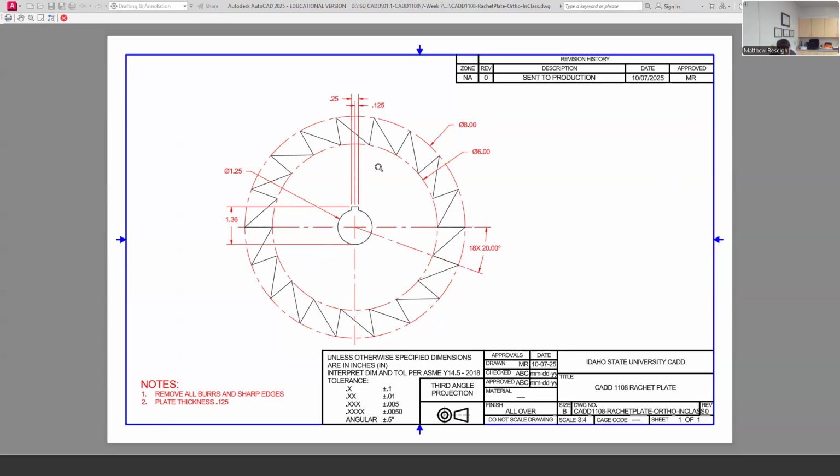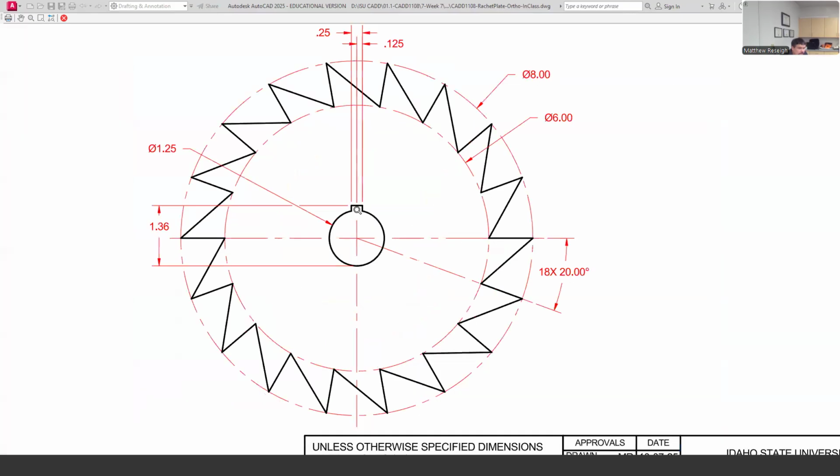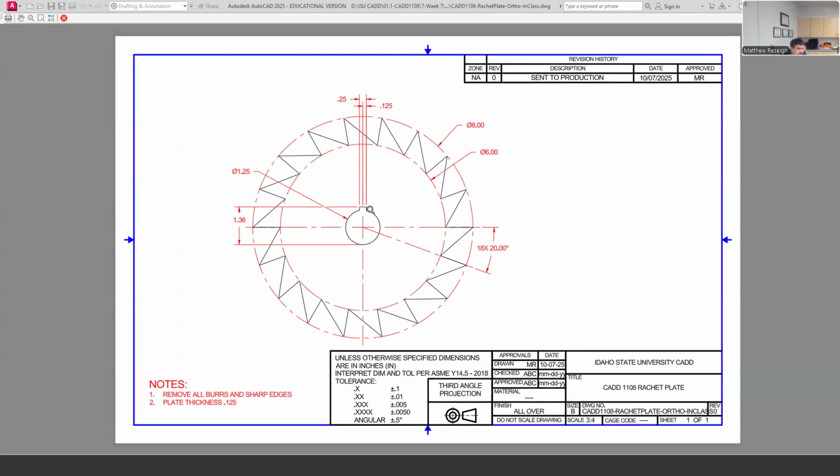The machinist's Bible is also probably going to have the information they need. If you show them this, they're going to know, okay, this is the keyway. They're going to look for the part that has the key seat, and they're also going to know from their information what the key would be. So some companies will not have to draw the key because that's just information obtainable by the machinist. But some places will actually draw the key that goes with this as well. It just depends on how complete they are. But really, with the information machinists have, they can determine what key will go in this and what the matching key seats will look like too.